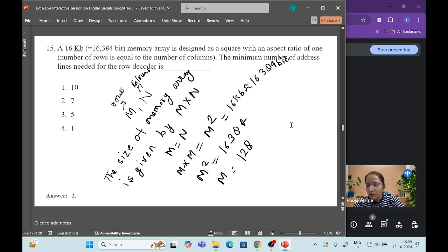Okay, so now the rows are addressed by address lines and all the registers of a particular row are handled by a data line. Now we need to find the number of flip-flops, or number of storage devices. For this 128, the number of flip-flops can be handled by log 2 m. So log 2 128, if you solve it further, you will get 7. That is the data line.